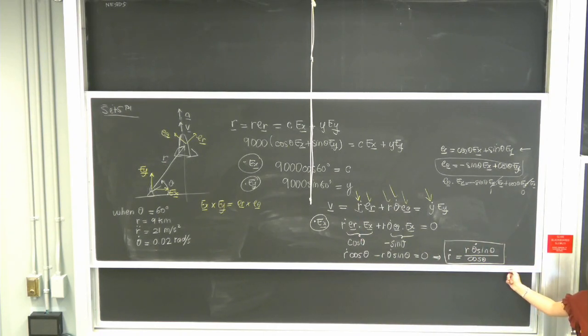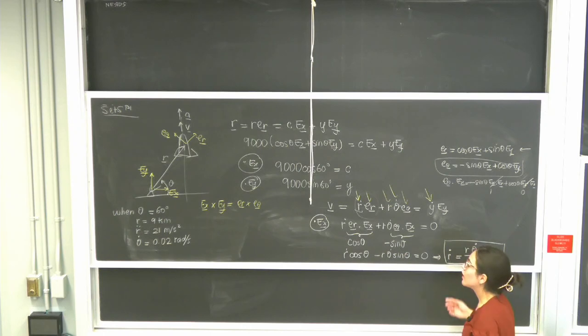say I wanted to find Y dot first. Which smart projection could I have taken to find Y dot without depending on R dot? So again, the question is, say I wanted to find Y dot first, which smart projection can I take so that my expression will not depend on R dot? Think about it. I want to solve for Y dot without depending on R dot. Raise your hand if you have the answer. Great. What is it? E theta. So if I project along E theta, will it get rid of this term? Yes. Great. So I'll project along E theta.